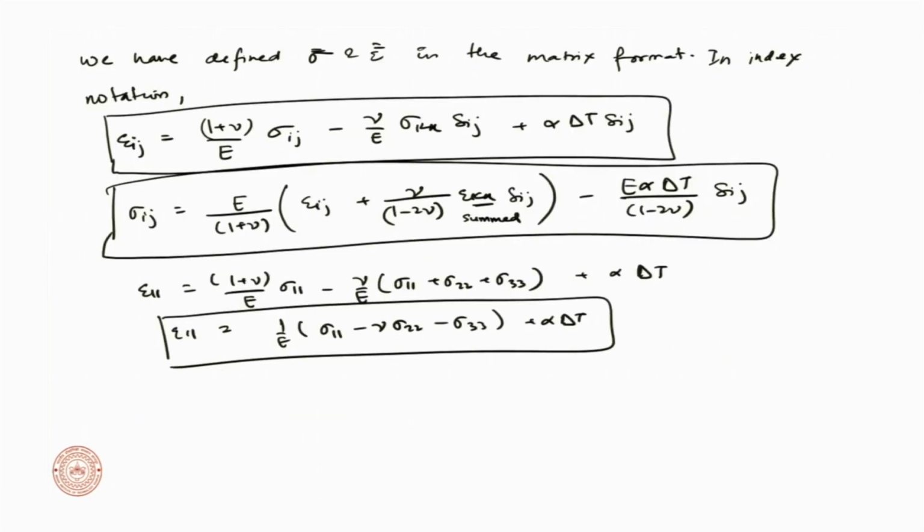Okay. So, we now have a confident model relating our displacements or our strain to our stress. That was the objective of the constitutive model. Okay. Now, we are writing this in a very big format. We can simplify this even further, using something called the stiffness tensor or the compliance tensor.